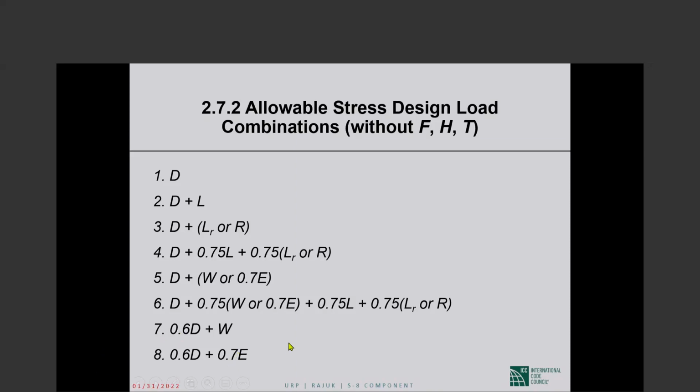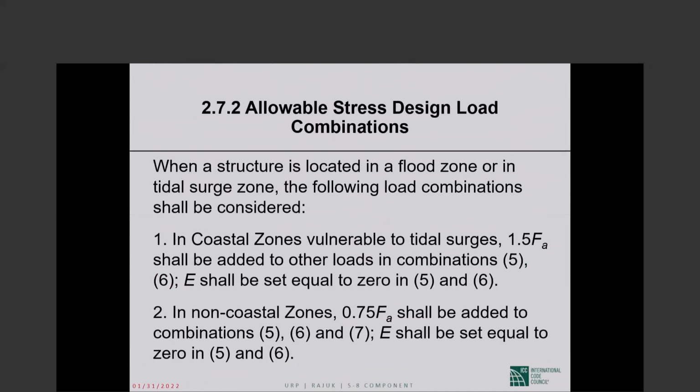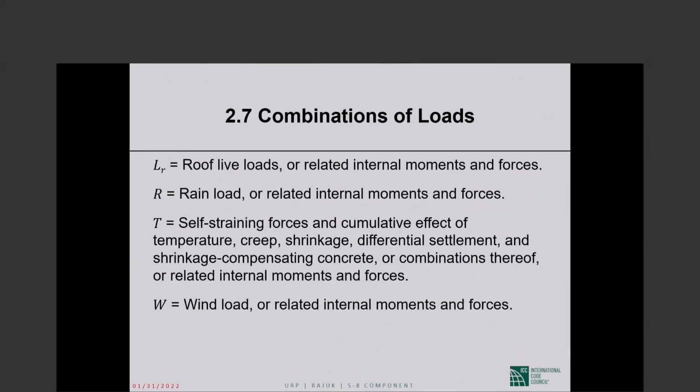So in ASD load combinations, you see that we rely on only 60% of the dead load to counteract service level wind or service level earthquake. That's pretty conservative.